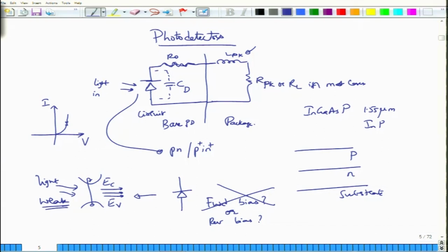to be proportional to the optical power that is incident, okay. So, to the optical power that is incident, you must generate a certain amount of current. It is interesting that it is the optical power that goes in, not the electric field. The reason is very simple. Power is proportional to intensity, intensity is proportional to the photon energy, and it is the energy which is the determining factor to take the electrons from the valence band to the conduction band.